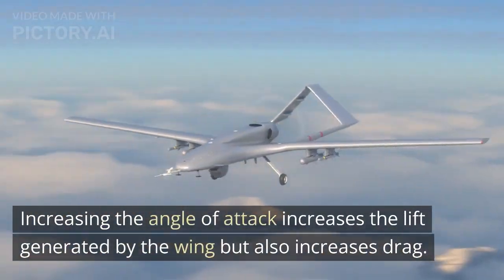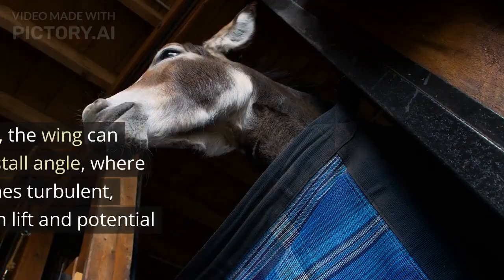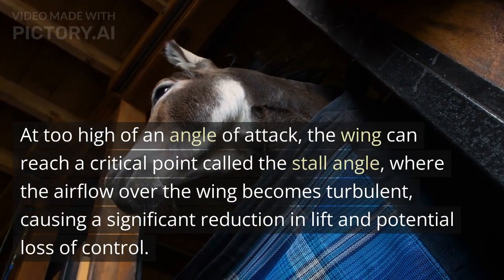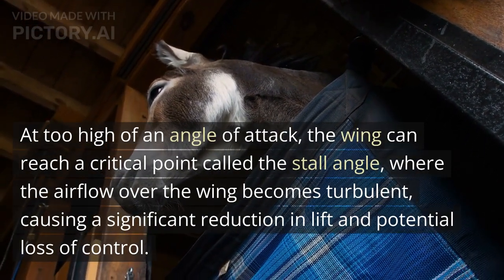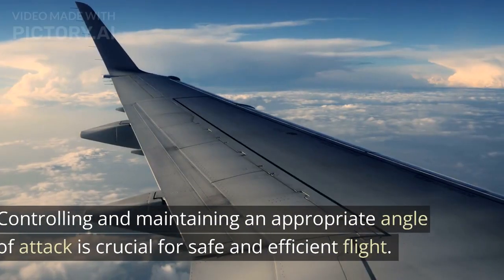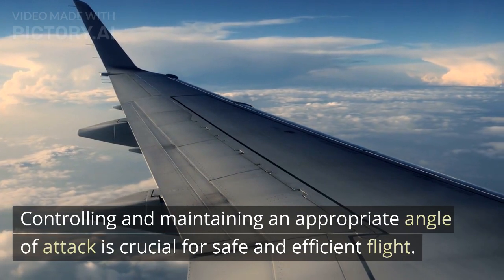Increasing the angle of attack increases the lift generated by the wing but also increases drag. At too high of an angle of attack, the wing can reach a critical point called the stall angle, where the airflow over the wing becomes turbulent, causing a significant reduction in lift and potential loss of control. Controlling and maintaining an appropriate angle of attack is crucial for safe and efficient flight.